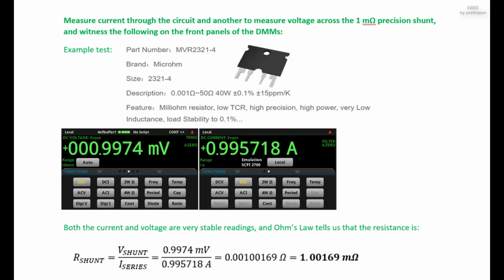One pair of terminals applies a known, calibrated current to the resistor, while the other pair senses the voltage drop across the resistor. Some laboratory quality ohm meters, especially milliohm meters, and even some of the better digital multimeters sense using 4 input terminals for this purpose, which may be used with special test leads. Each of the 2 so-called Kelvin clips has a pair of jaws insulated from each other. One side of each clip applies the measuring current, while the other connections are only to sense the voltage drop. The resistance is again calculated using Ohm's law as the measured voltage divided by the applied current.